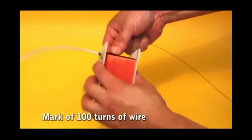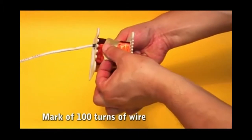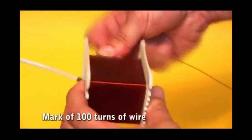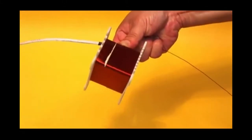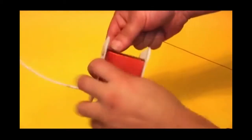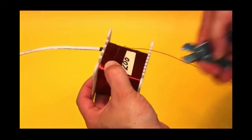We recommend that every 100 turns of wire, stick a piece of tape with the number of turns. If you lose track of the turns, you only have to return to the last tape and its number of turns. When you finish all the turns of the primary winding, cut the wire.